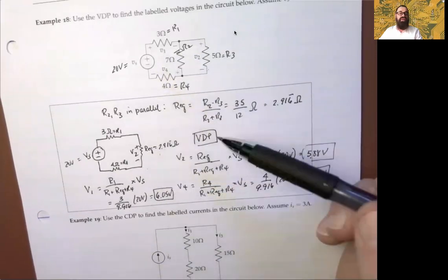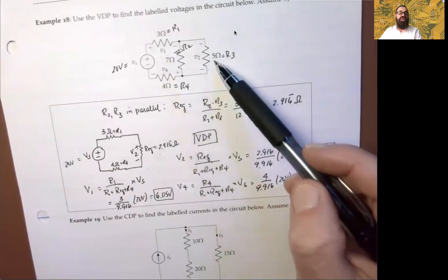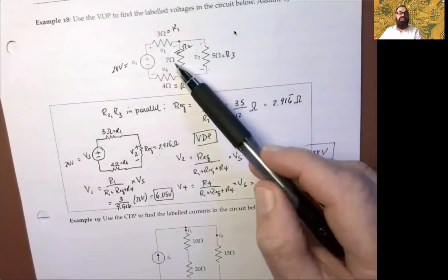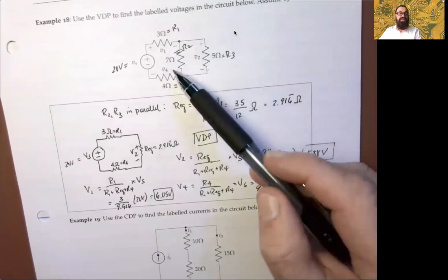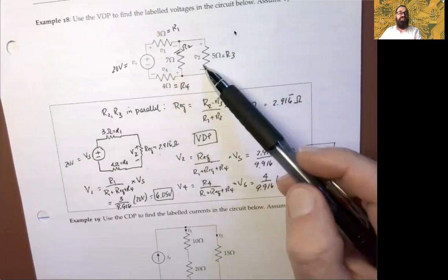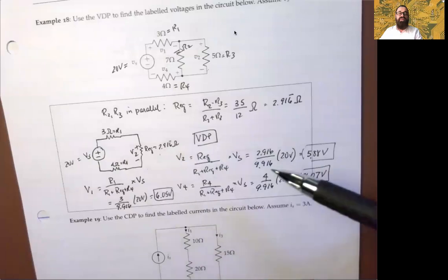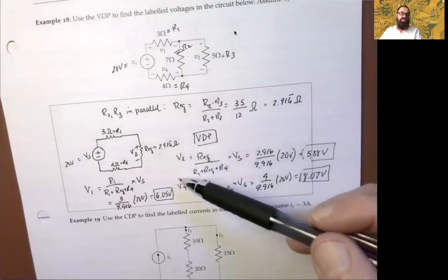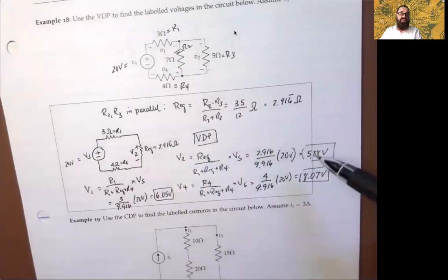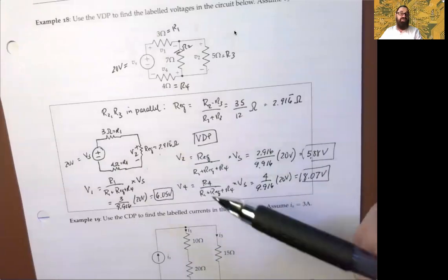So it's kind of interesting that the voltage is highest across the 4 ohm. You might have thought, well, wait a second, these have higher resistances, but they are in parallel, right? So if we think about the 20 volts, we have 5, that's almost 13. I mean, you can see how this is summing. These 3 are definitely summing to be close to 20 volts.